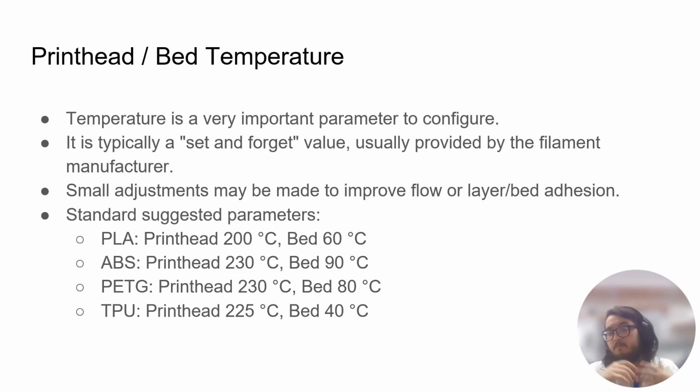But instead of you going and learning material science and polymer science and figuring this out, you can just read the box that your filament came with, and it's gonna probably tell you which temperature for the print bed and which temperature for the print head. And we're very happy that modern slicers have this. We just select the material and they're gonna have a fine-tuned temperature for us for the material we're gonna be using. PLA, ABS, PETG, TPU, PP, nylon, and all those different types of filaments, HIPS, ASA, whatever.